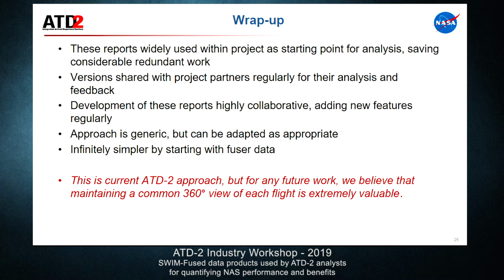One question: how are departure queue times calculated? Departure queue times are always benchmarked against what we call the unimpeded taxi time. Prior to an aircraft actually taking off, we will have a predicted target takeoff time, TTOT. We can compare the target takeoff time to what we call the unimpeded takeoff time, the UTOT, and the difference between the target takeoff time and the unimpeded takeoff time is our estimate of the queue.